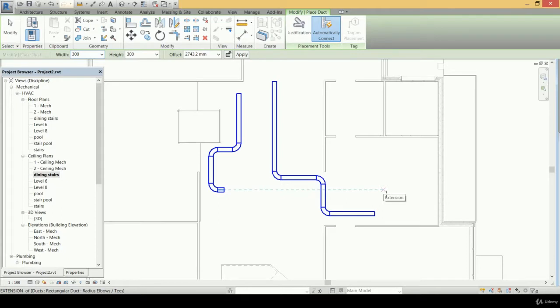to the same ceiling in the plumbing ceilings, we will find that this duct appears in the plumbing ceiling. But this is an undesired case, as we need the ducts to appear only in the HVAC ceiling because the ducts are used in the HVAC design. And also we need the pipes, for example, to appear only in the plumbing ceiling, as we use the pipes in the plumbing, not in the HVAC design.